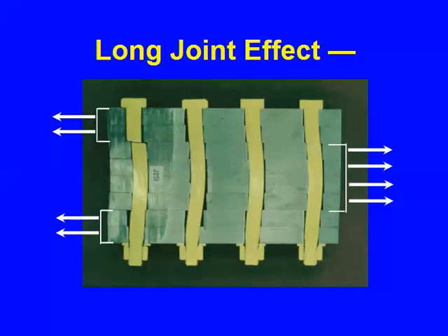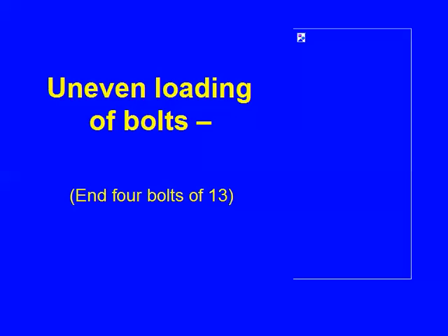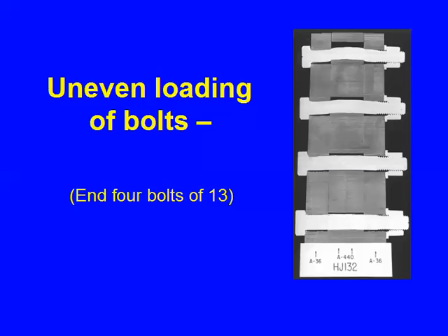It's the same thing, but with a much smaller joint. This is the one that's 13. The previous one was 25. It's coming back to me now. So this was 13 bolts in line, and the proportions were different. You have to keep in mind that what we see is a reflection of the proportion of the bolts as reflected in the shear capacity and the plates. All right, 1-inch plates again.